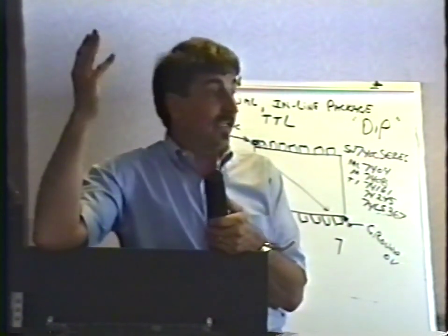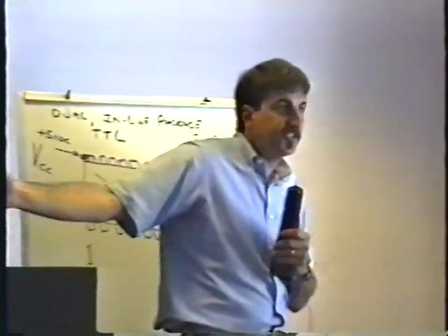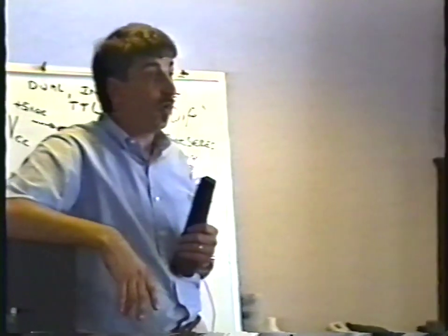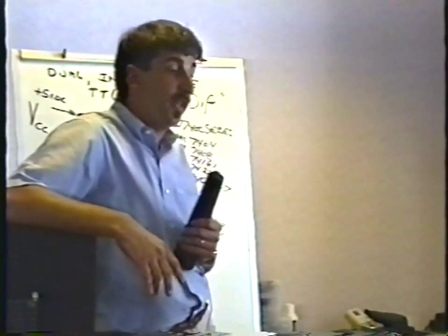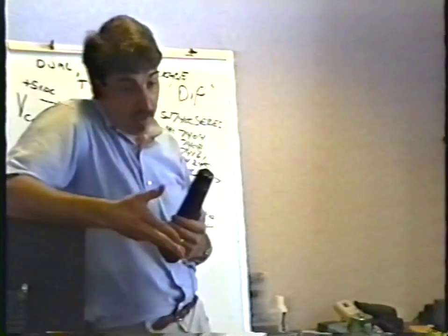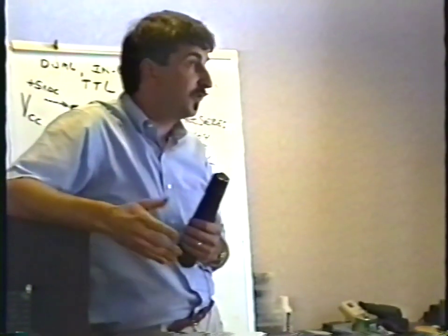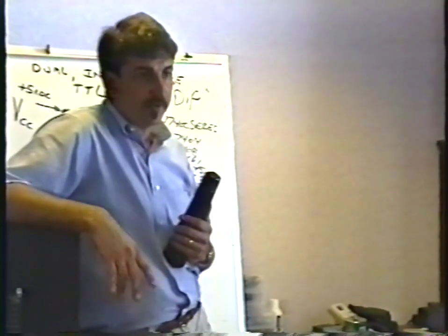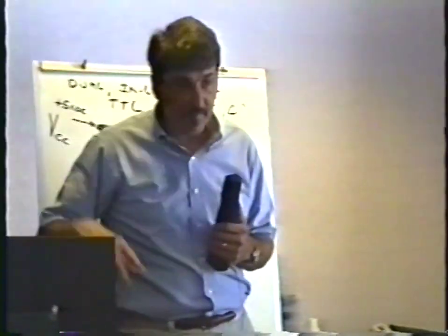And I know, like I said, I'm not a genius. I see this 100 times. I've changed C702 in 100 different monitors. Because I do these monitor labs on the road all the time, I see tons and tons of monitors. It's almost all I work on, really. I work on monitors in the field. I mean on the road when I'm here doing the classes. And when I get home, most of my repair work is monitors, because the other people can do the simple jazz, and the monitors, they just don't know. So I've changed this cap a ton of times.